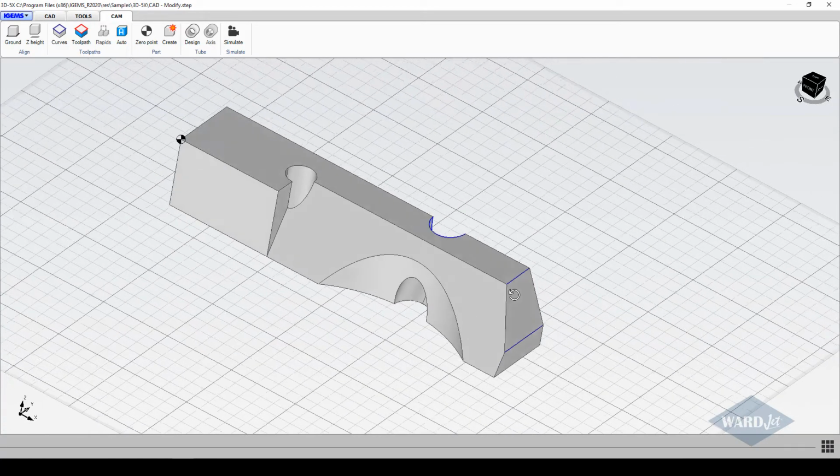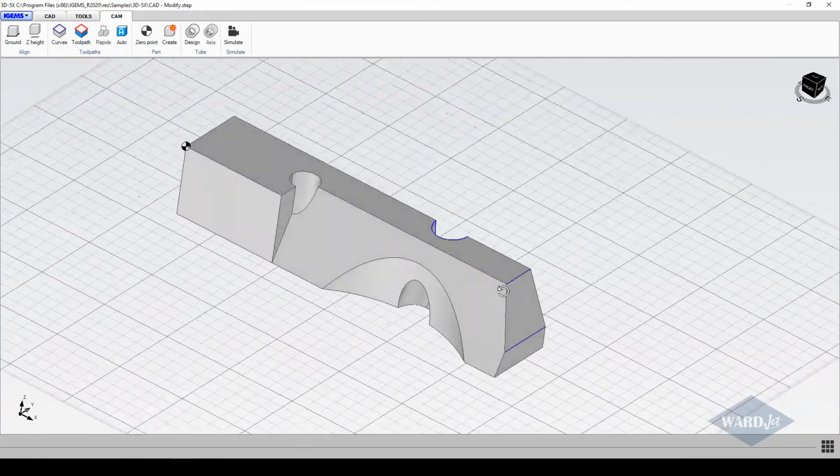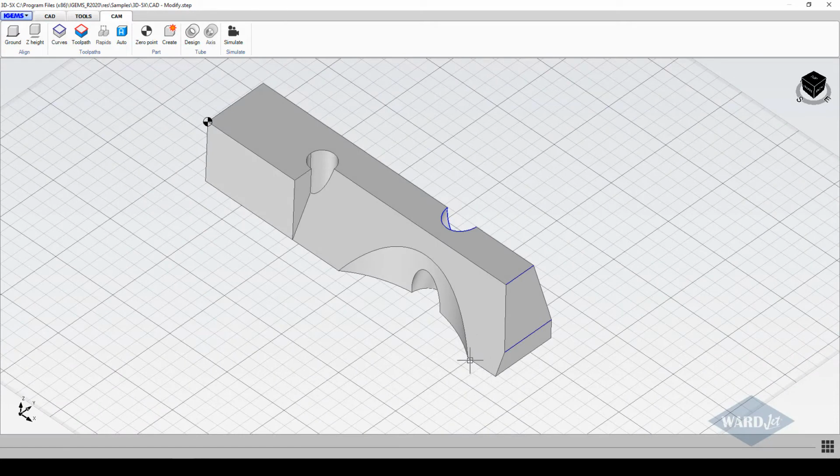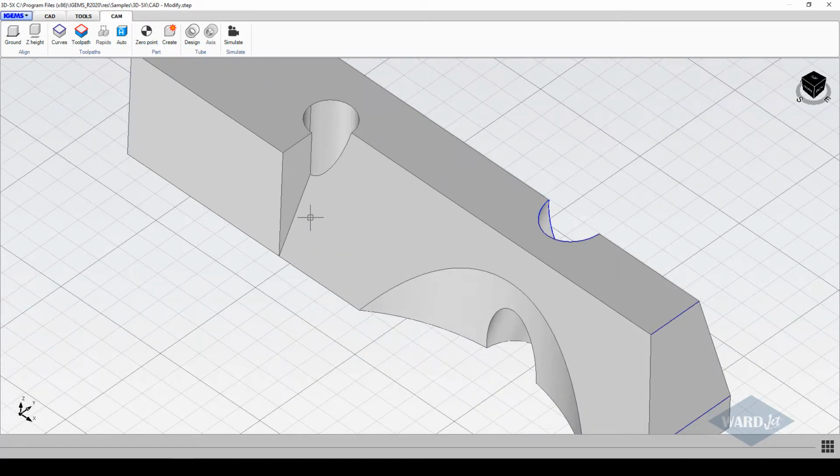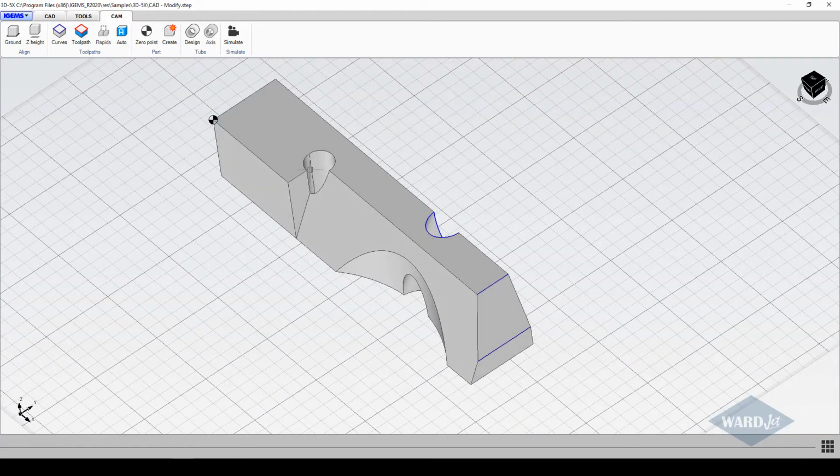So we can extend that edge a bit, and then for the bottom edge, we'll basically again need to draw in a line as we're picking our edges and go across here. And then the final thing is when we're coming out, we'll be able to pick an edge and define an edge along here, but then again, for best cut quality, we'd probably want to have that same length of an edge projecting out here so that that head stays at a nice fixed angle all the way through this entire cut.